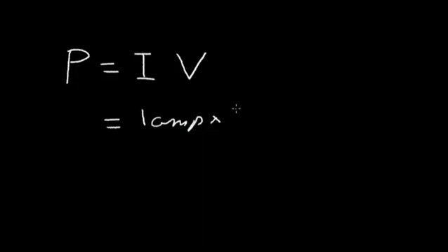Now a similar thing happens in a resistor, not to such a degree, but to a lesser degree. As the electrons collide with the particles, they produce heat, just like that meteor entering the Earth's atmosphere. And there's a very simple equation that we can use to calculate the energy or the power dissipated by this resistor. The equation is P for power is equal to the current flowing through the resistor times the voltage across the resistor. In our simple example, the power would be 1 amp times 1 volt across the resistor, which would be equal to 1 watt. 1 watt of power dissipation in the resistor.